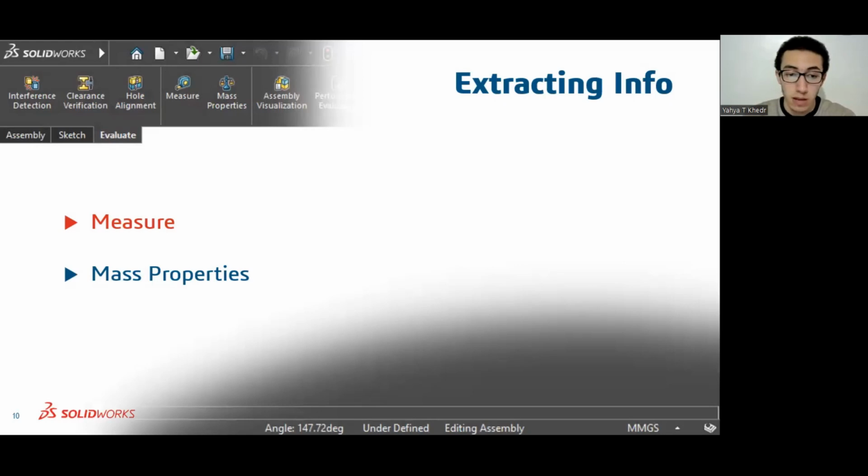So for example, if I select 2 faces or 2 edges, and there's a certain angle between them, I can see that angle as soon as possible without needing to open the measure tool, just by taking a glance at the lower bottom right corner of my screen. I'm going to get the angle is XYZ, or let's say I selected an edge, so it's going to tell me its length, for example, and stuff like that. So this is a quick way to know certain dimensions that you might need without needing to open the measure tool or pin it to the side.